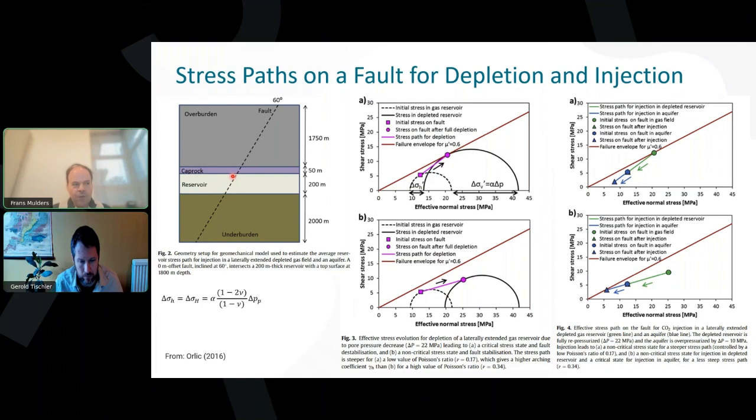And therefore also maybe lower temperatures near the wellbore. And if that continues long enough, it actually goes away from near wellbore effects to reservoir effects. So injection rate definitely can influence your pore pressure and temperature distribution throughout the field over time, and therefore also the stress changes.